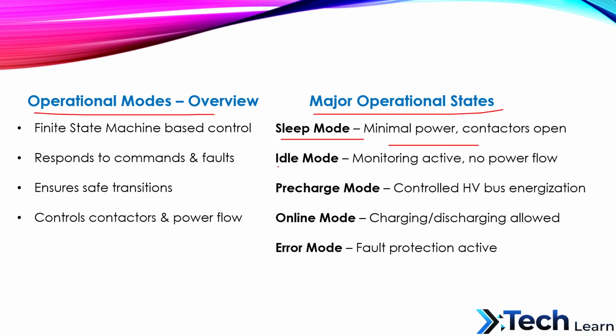Now coming to the idle mode. In idle mode, contactors are still open. However, monitoring circuits are active. Voltage, temperature, and SOC are updated. Fault detection is running. Communication buses are active. This ensures the battery is safe before the connection.